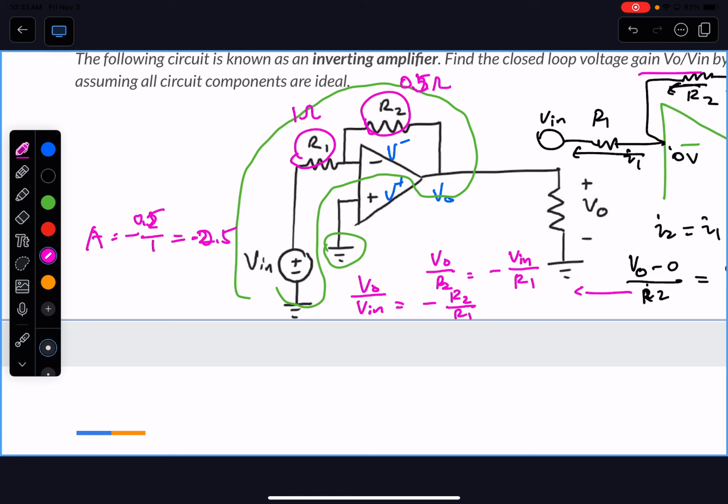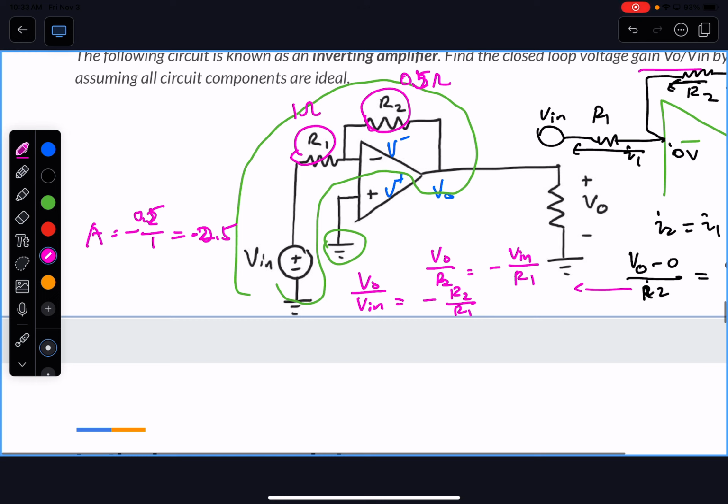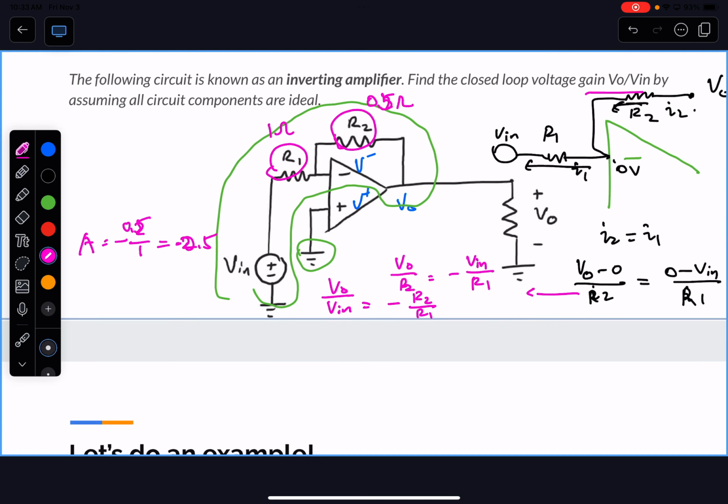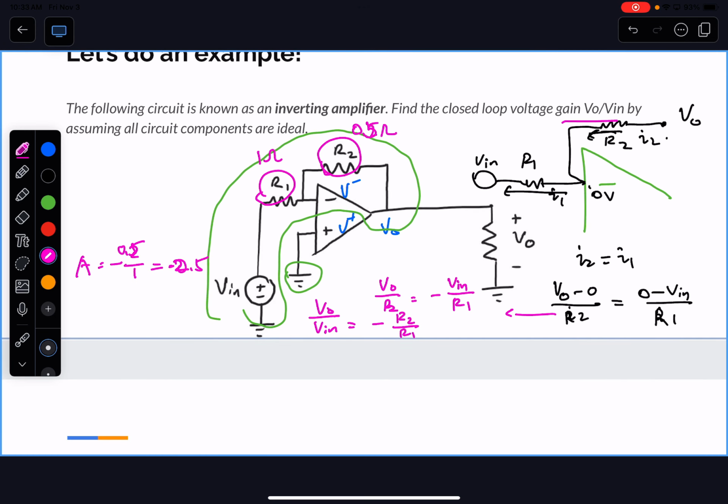Unfortunately, with the negative feedback, you cannot avoid flipping the sign of the signal, because you cannot choose a negative R value. R has to be positive, so you have to deal with it. We will talk about how to not get a negative output signal in just a second. Does that make sense so far? This is a special case where your wiring is directly to ground. That's how you control it.